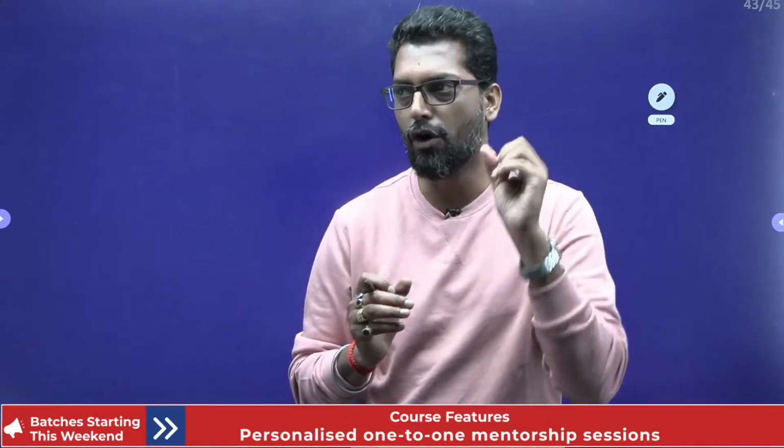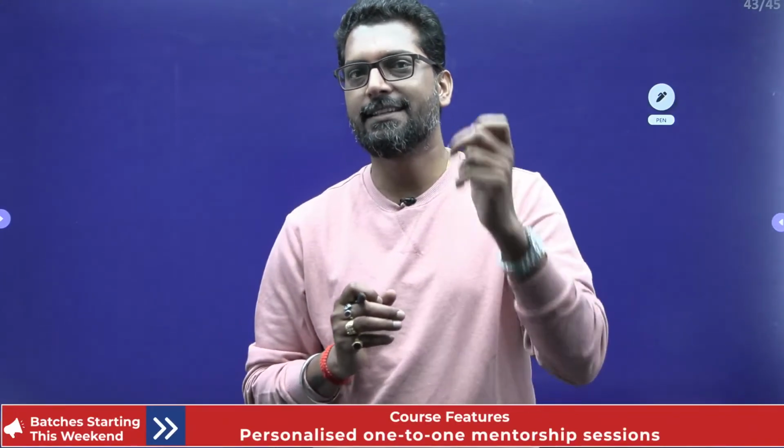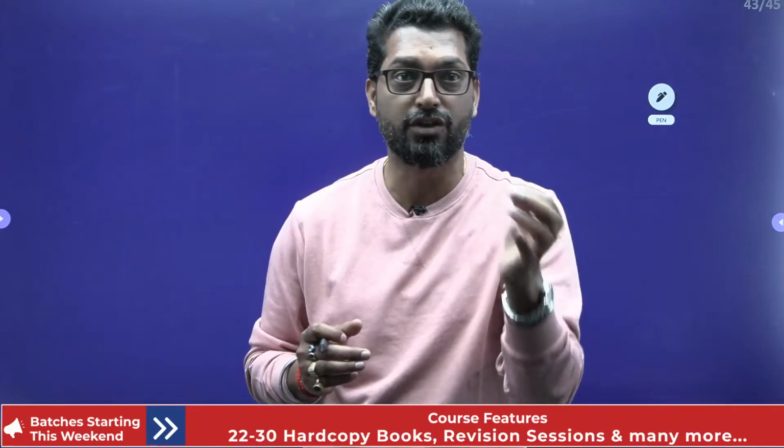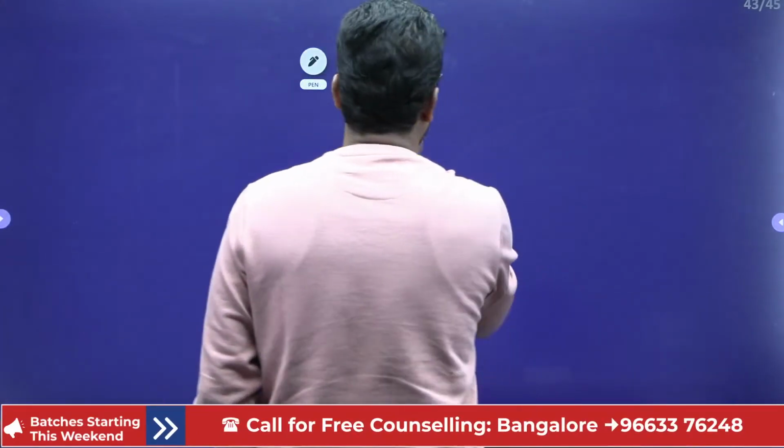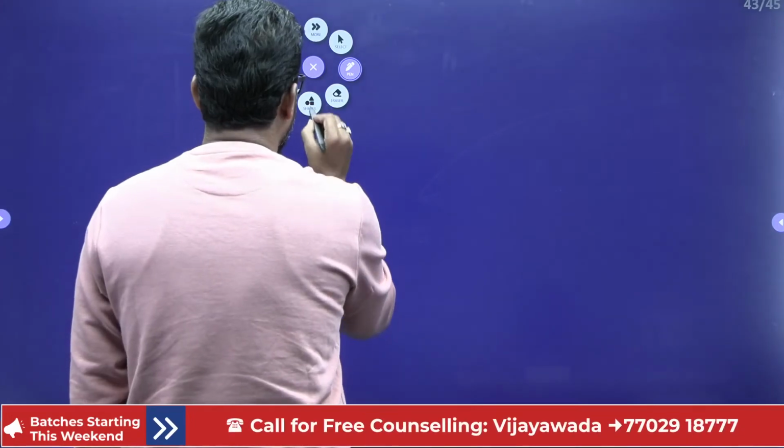Mind it, it is not necessary that TdS equal to dH minus VdP will be applicable only for an open system and TdS equal to dU plus PdV applicable for a closed system. No, it is a wrong concept. So keep in mind, that is the one note here. I will write one note here.